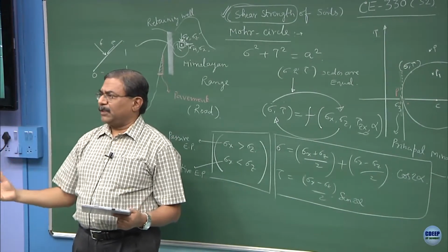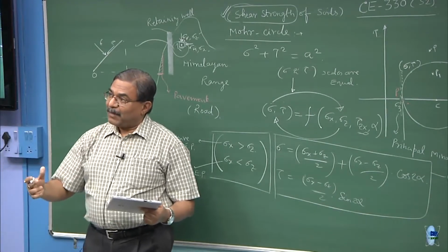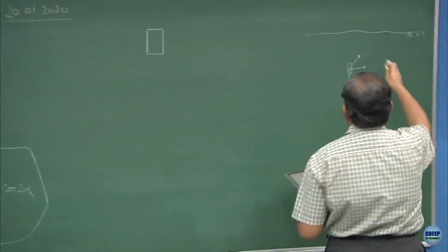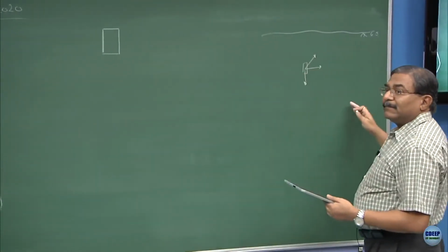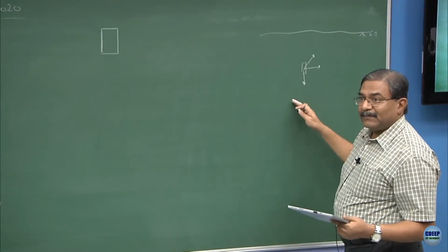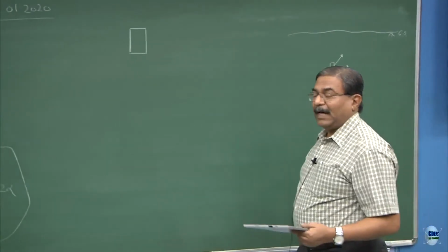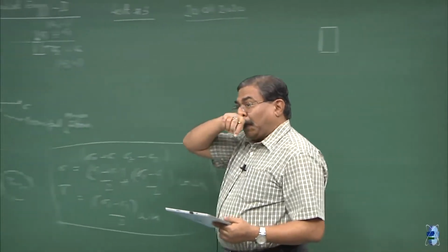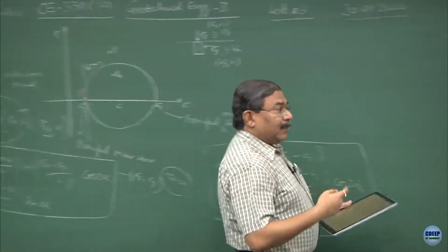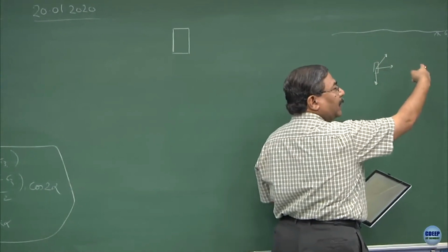Triaxial is a very realistic situation, but highly complicated to deal with, because if you remember, first of all we are dealing with a very complicated material like soils, where we assume them as isotropic homogeneous, clear? We assumed isotropic homogeneous, you might be violating these situations, clear? So the material is very complicated, and then the complication comes in the form of the 3-dimensional analysis.